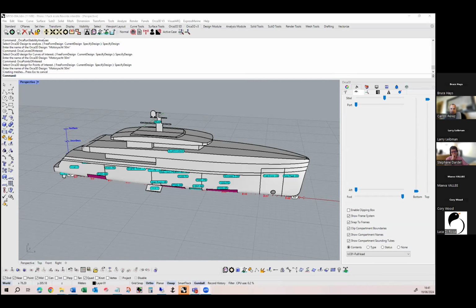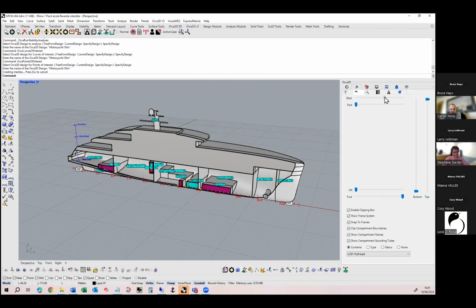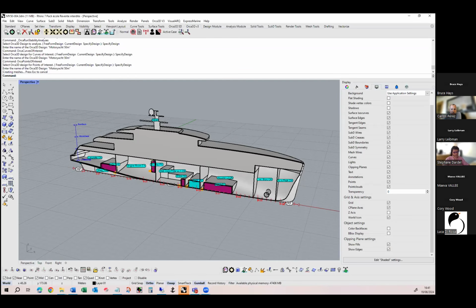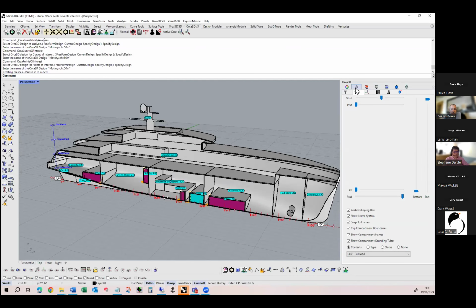And they could join those and essentially create a compartment that is the insulation that has a permeability of 0. So in that case, unlike shell thickness, it's actually a pretty significant amount of volume that you need to account for. And it shows that when you're doing the calculations on surfaces rather than sections, it's easier to handle cases like that.